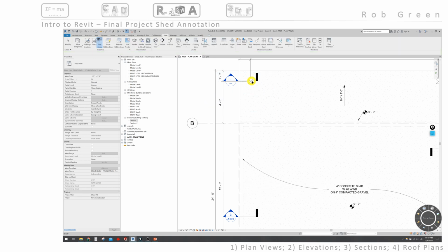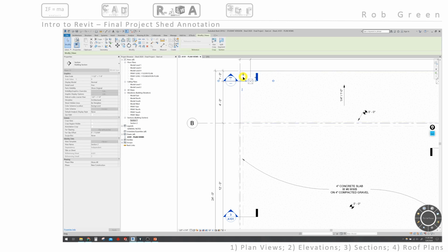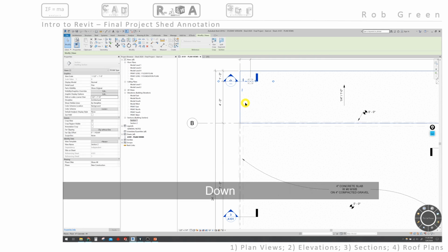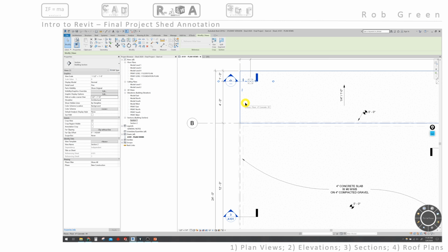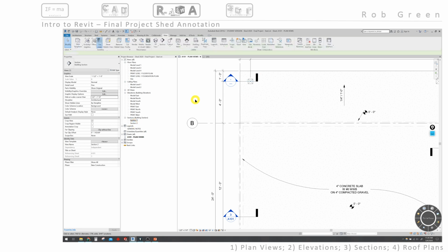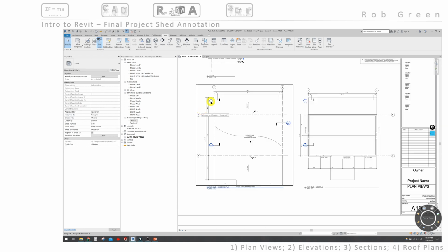I have that view. I now am going to shrink down my view even more so that I basically see no depth in this section. And then I'm going to nudge it down so it rests directly on the dimension line, hopefully so that there's no lack of clarity there. And it is, of course, as you can see in my project browser, the only other section that exists. It's section 2. And here I can deactivate the view now and drag section 2 onto my drawing sheet.